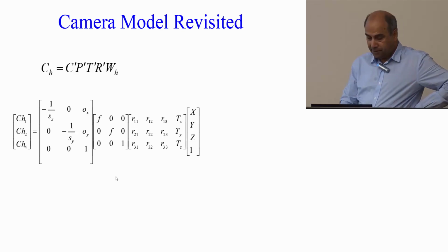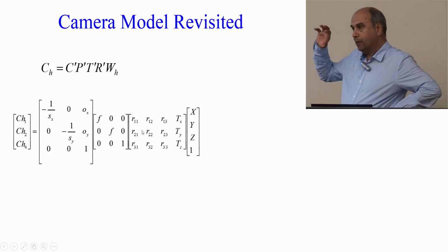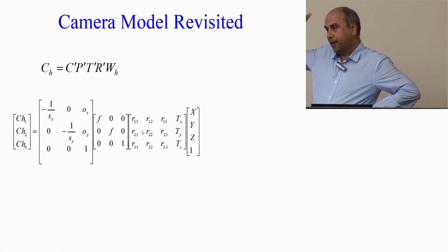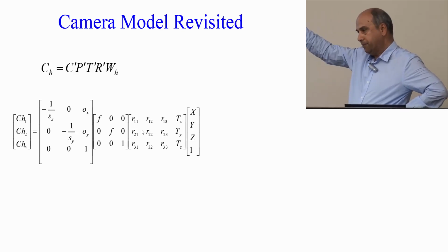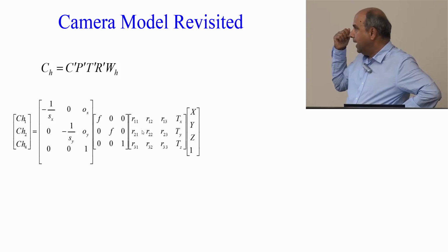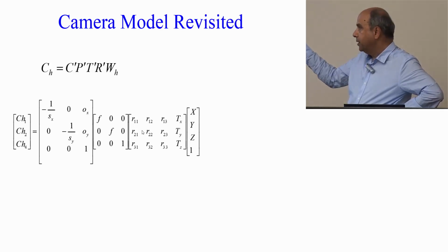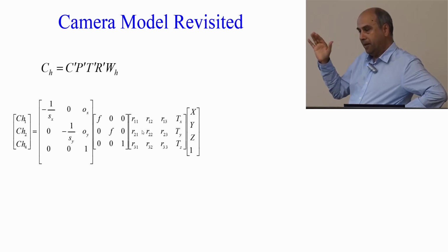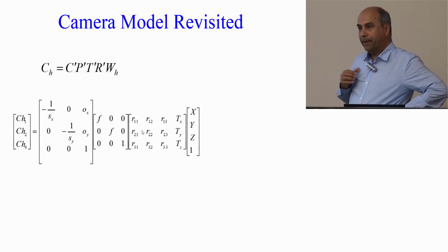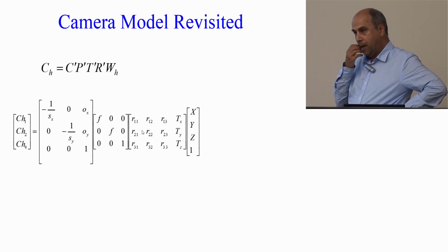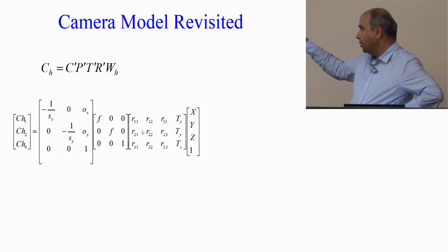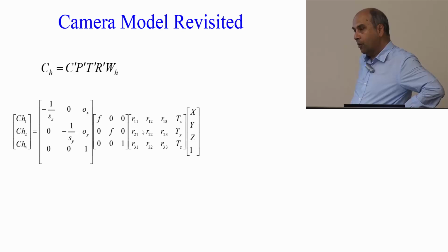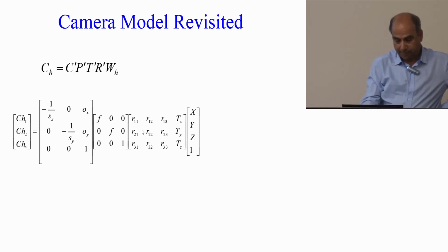and this. So first thing here is we are looking at the rotation, any rotation. The first example I gave you a long time ago was a particular rotation on the z-axis, y-axis. Now you have a rotation matrix, which captures any rotation, a 3 by 3 matrix. And then we have the perspective transformation, which is F. And then from camera to image, we have that matrix. So this is a kind of complete camera model, which will capture anything. And that's more general. And again, we have the homogeneous world coordinates, and the image coordinates in the homogeneous system.